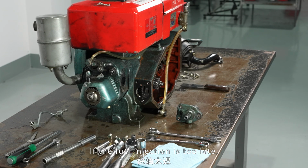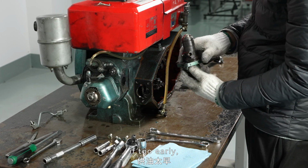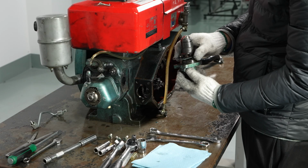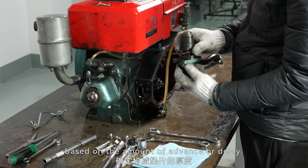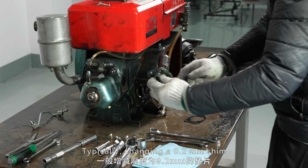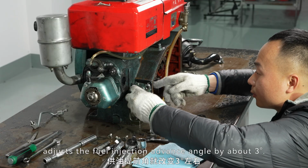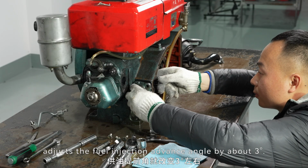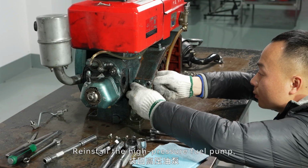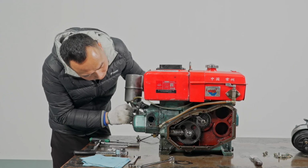If the fuel injection is too late, reduce the thickness of the shim. If too early, increase the thickness. Adjust the shim thickness based on the amount of advance or delay. Typically, changing a 0.2 mm shim adjusts the fuel injection advance angle by about 3 degrees. Reinstall the high-pressure fuel pump, rotate the flywheel, and recheck.